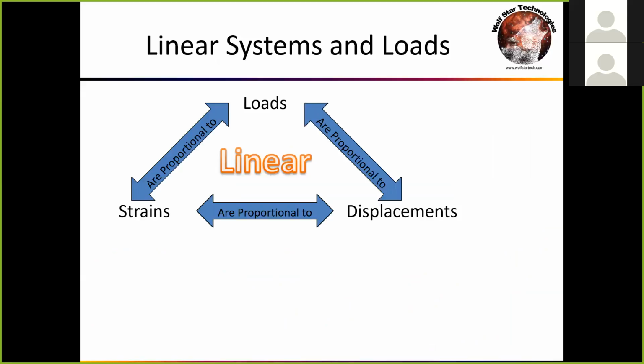But we are going to turn our part into a load transducer. So we're going to stay in nominal strain areas on the part, and we're going to stay away from high strain gradients. We're going to stay away from where we've got welds. We're going to stay away from bolted joints. We're going to stay away from contact locations. We're just going to be out in nice nominal areas of the part because we're turning the part into a load transducer. Now, the loading can be as nonlinear as anything. Loading can be sinusoidal loading, it could be ramp loading, it could be impact loading. That doesn't matter. I just need the strain response to be linear.